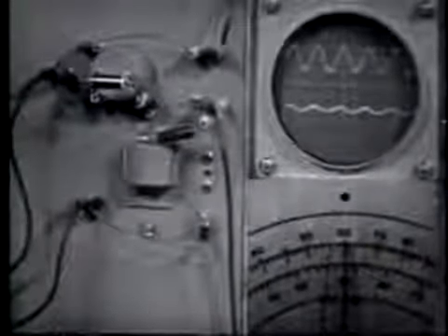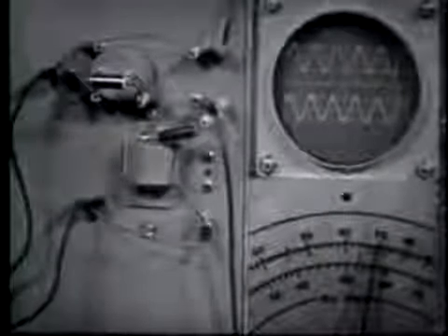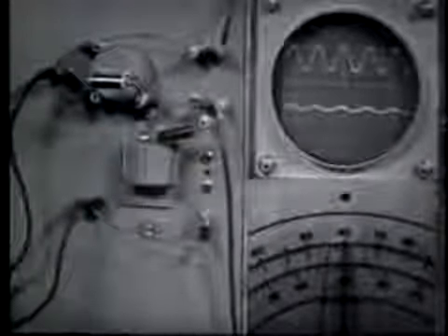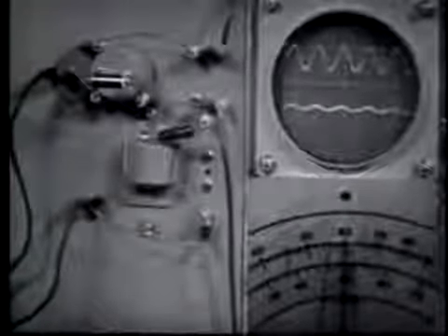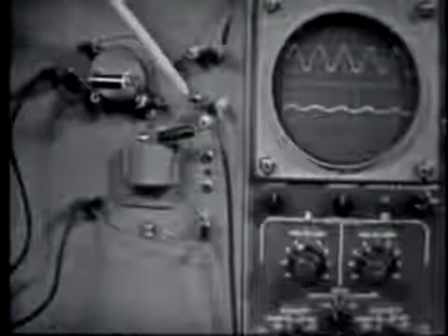Just this. This L section band reject filter rejects a band of frequencies from about 500 hertz up to about 700 hertz. Now since the specific frequency we want to reject is 600 hertz, this circuit is not too precise, is it? So let's make a T section from this basic L section and see if we can improve the frequency response. Now to make the T section, we'll need another parallel tank in the output leg of the series position, and we'll need to move our series tank over to the junction between the 2 parallel tanks.